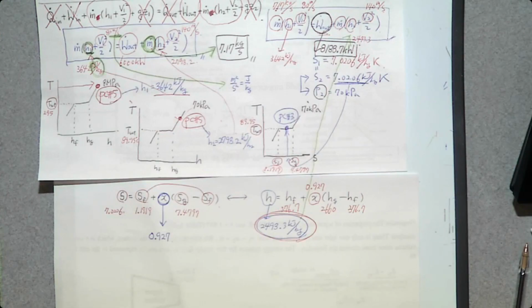The actual power could be less than that because in reality, there are many irreversibilities. But the goal is, if your present turbine can produce 6,000 kilowatts, then you know that you can go up. It is possible, theoretically. And what is the maximum value? 8,188. Then, how close is this turbine to an isentropic turbine?